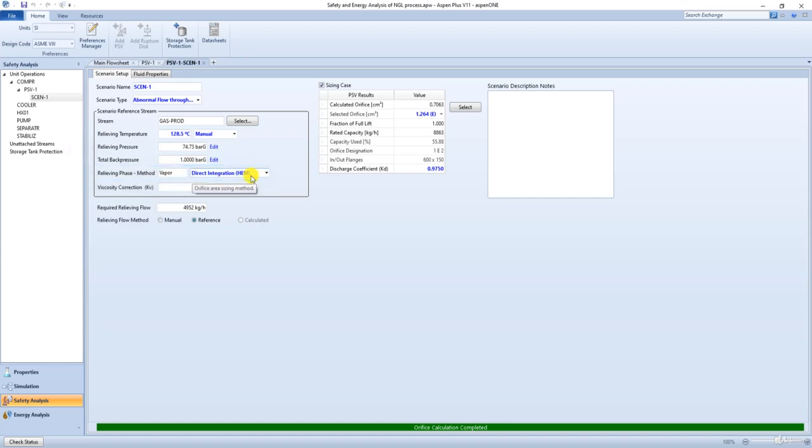The equations used with this option are based on the homogeneous equilibrium method, which assumes the fluid mixture behaves as a pseudo-single-phase fluid with a density that is the volume averaged density of the two phases. This method is based on the assumption that thermal and mechanical equilibrium exists as the two-phase fluid passes through the PSV. For high momentum discharges of two-phase systems in nozzles longer than 4 inches, both thermal and mechanical equilibrium can be assumed. These assumptions correspond to the homogeneous equilibrium flow model.